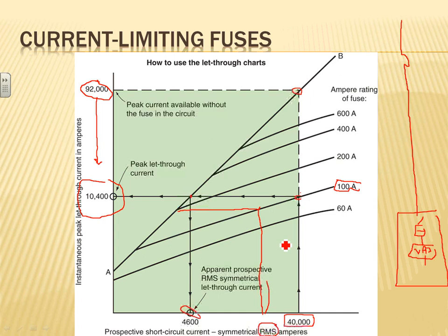Another thing is that they don't allow you to just submit the curve and say, this is what we did. They want you to stamp and sign that as a PE right on that curve and basically take responsibility for the performance of that fuse, which gets scary. I hear you, especially with current limiting.